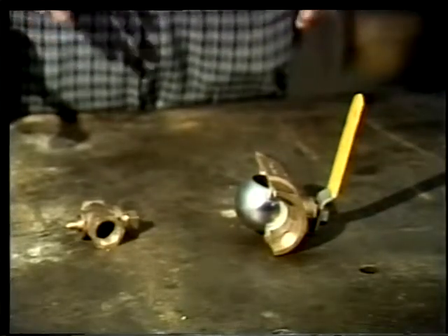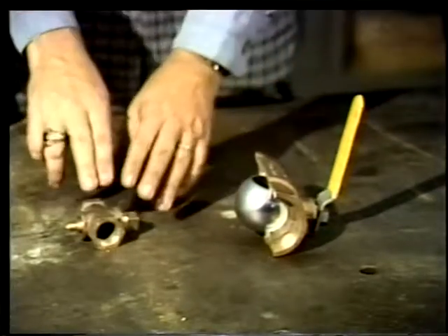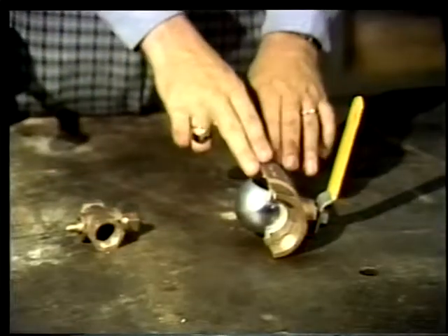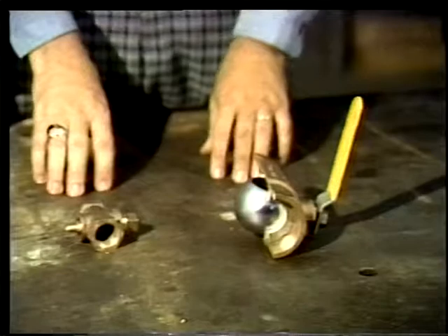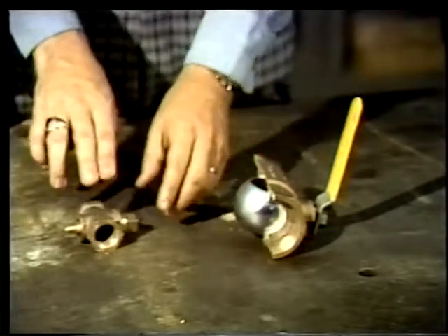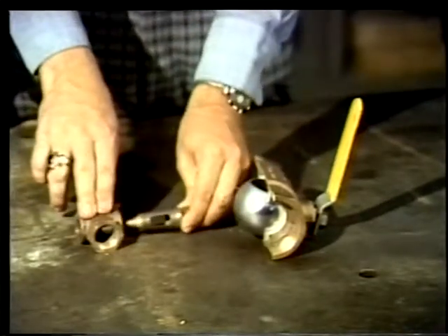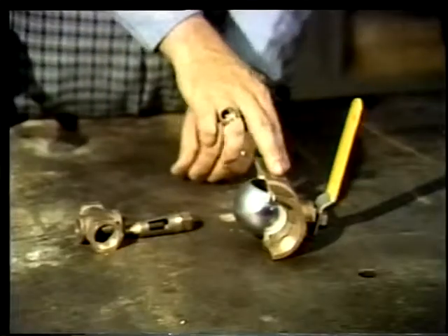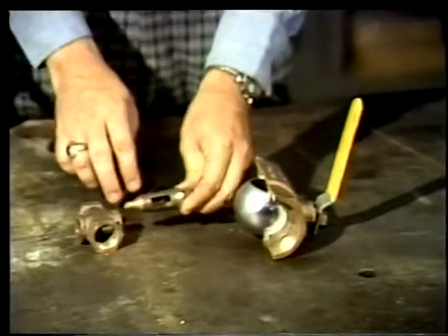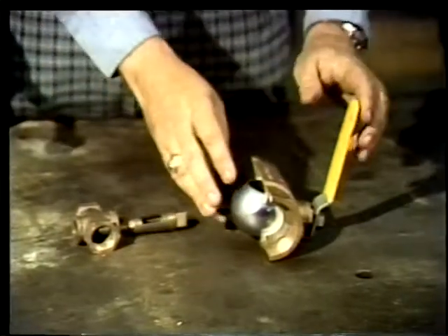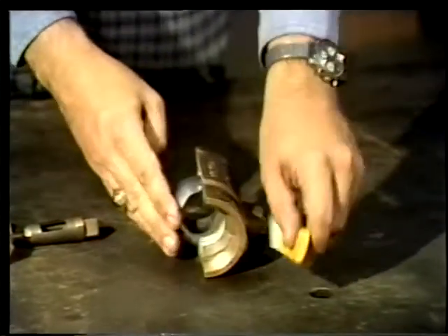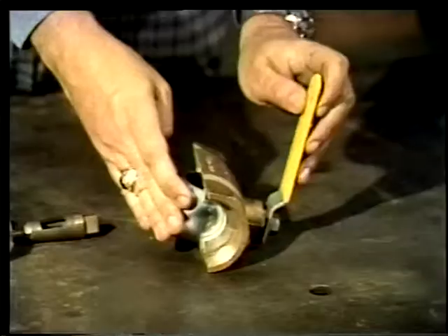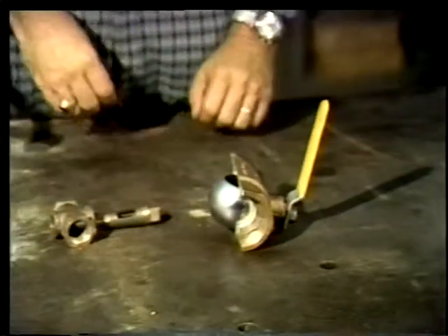Now we're going to look at two valves that are very much alike, a plug valve and a ball valve. And in contrast to most other types of valve, they do not have discs which raise and lower. The plugs on these valves, or the ball in this case, open by rotation. And when the valve is actuated, the ball makes a quarter turn, starting and stopping the flow very quickly.